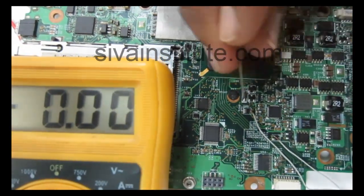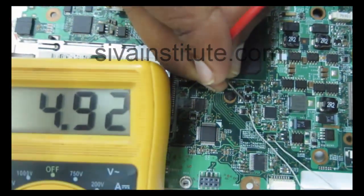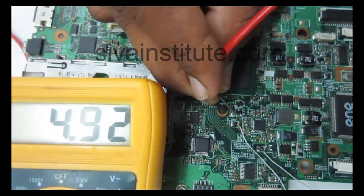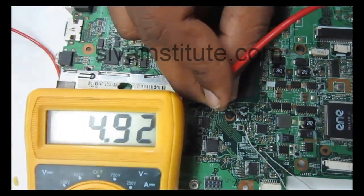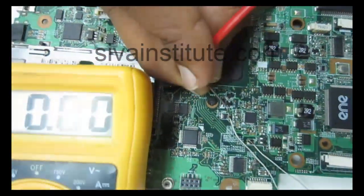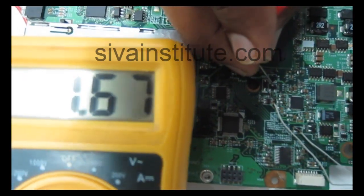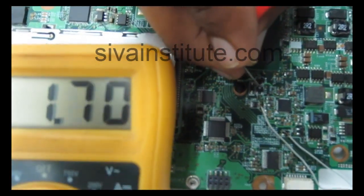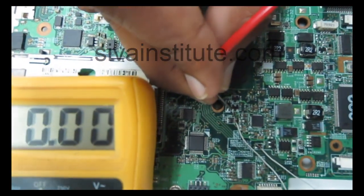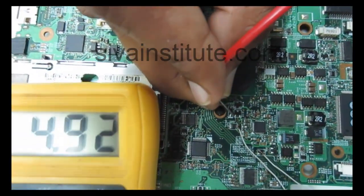Gate voltage 4.9. I will give the S5 command. This voltage goes to 0. See here, this voltage goes to 0. Drain voltage will come. After that it will start functioning. Gate voltage now 0. Without the command, gate voltage is 4.9 volts.